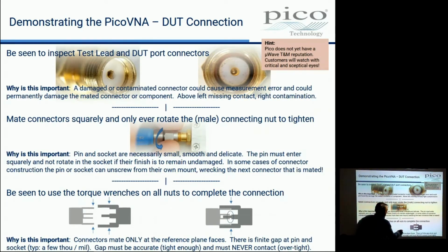When they are tightened properly, those two faces are touching, but the pin, it has a shoulder that does not quite touch the socket. You want a gap of about 1/1000th of an inch. What's that in millimeters, anybody? Pretty small. Can't remember in millimeters. Pretty small gap.